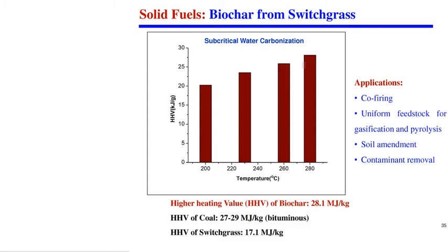And typical thermal dryers use more energy per kilogram of evaporation, roughly 3.3 to 4 megajoules per kg, just for removing water. So is there any process where we don't have to remove this water? Can we use this water? Yeah, hydrothermal technology can be one of the options here.